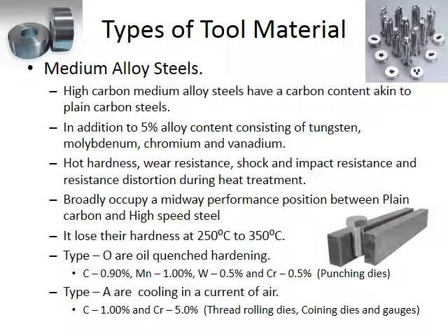The third important point is hot hardness and wear resistance, shock and impact resistance, and resistance to distortion during heat treatment. It broadly occupies the midway performance position between plain carbon and high-speed steel. The next point is that it loses its hardness at 250 to 350 degrees centigrade.